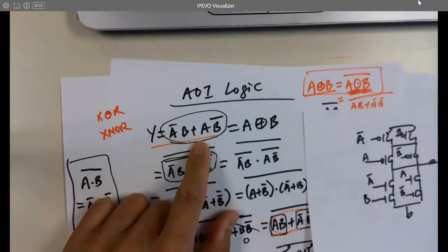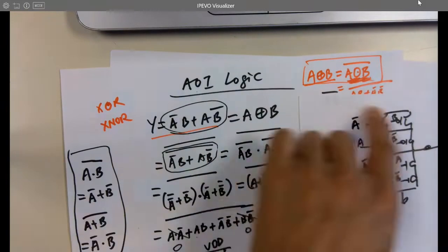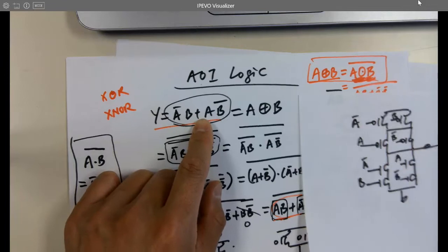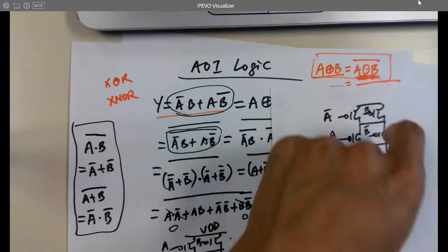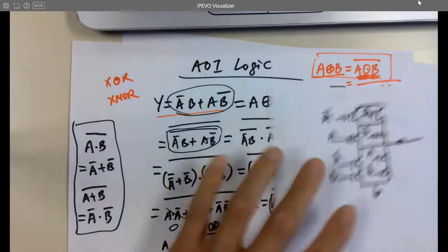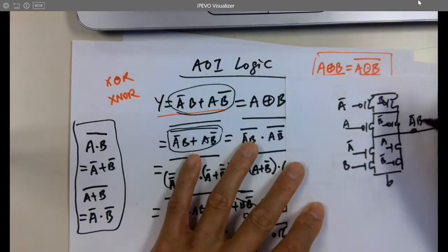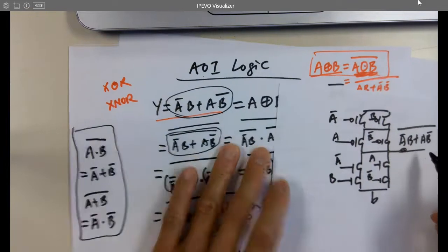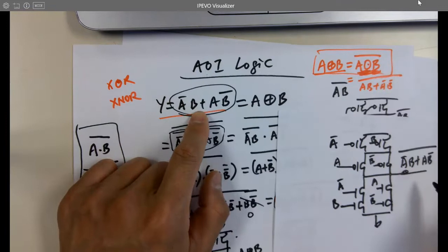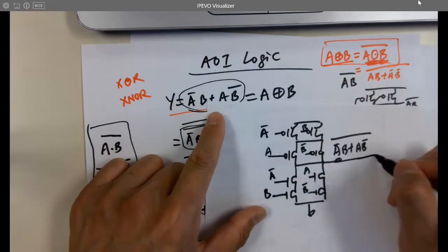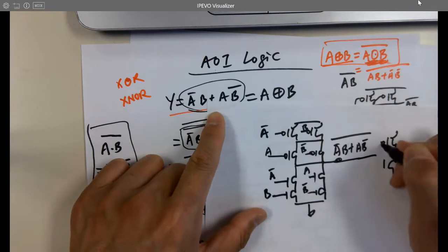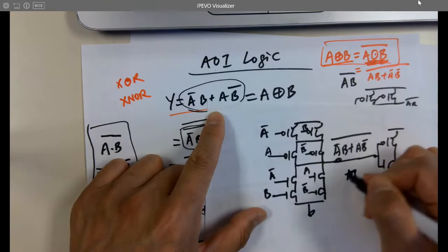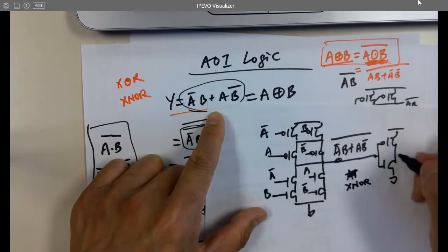We were looking at this logic equation to form this circuit, right? Does this one have a bar on the top? No. So when we look at this equation to form a circuit, this is what this circuit does. However, we are trying to get this logic, so we have to add an inverter here to make X work. So this is actually XNOR. This becomes XOR.